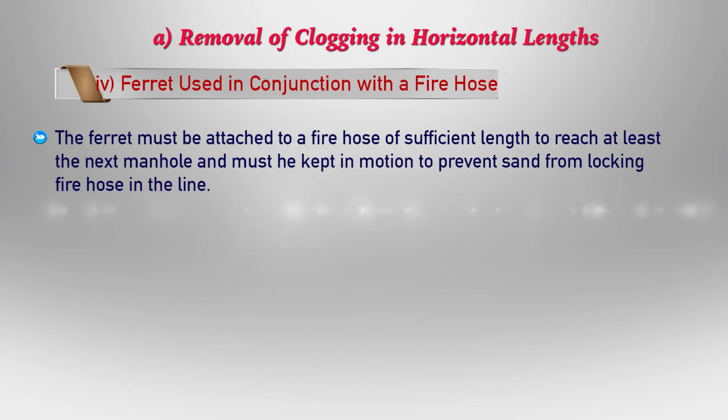The ferret must be attached to a fire hose of sufficient length to reach at least the next manhole and must be kept in motion to prevent sand from blocking the fire hose in the line.